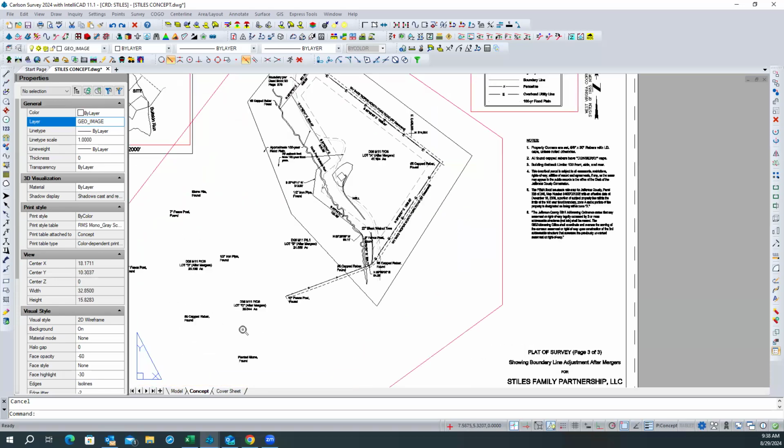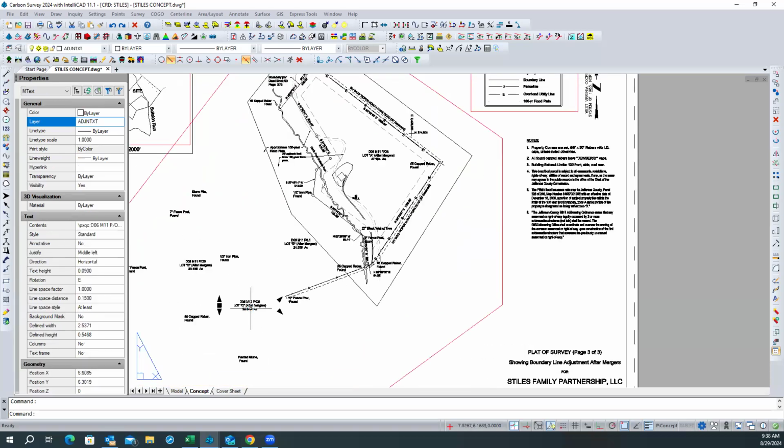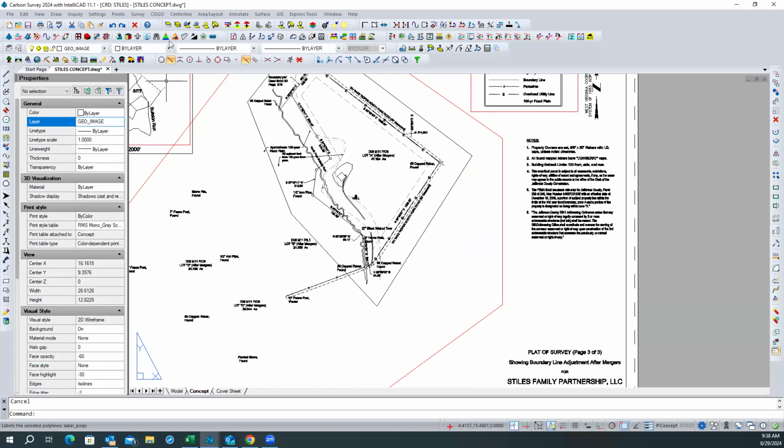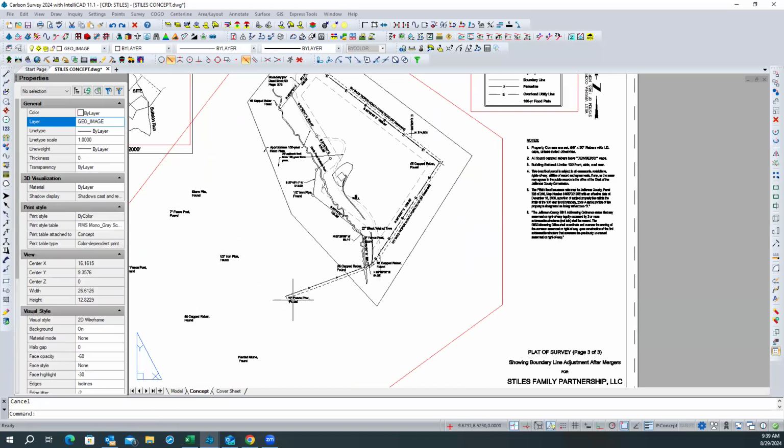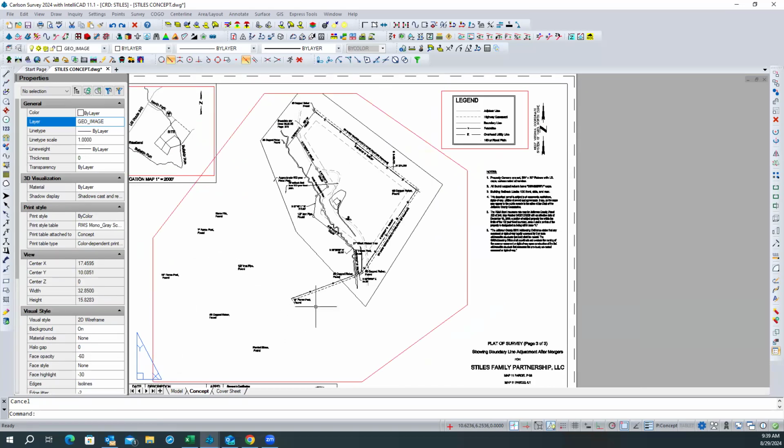It already froze a joiner, and now this one is on a joined text. So we'll freeze that one as well. What's this one on now? This is on boundary. Those are corners. They can be erased. We won't need those for this drawing.